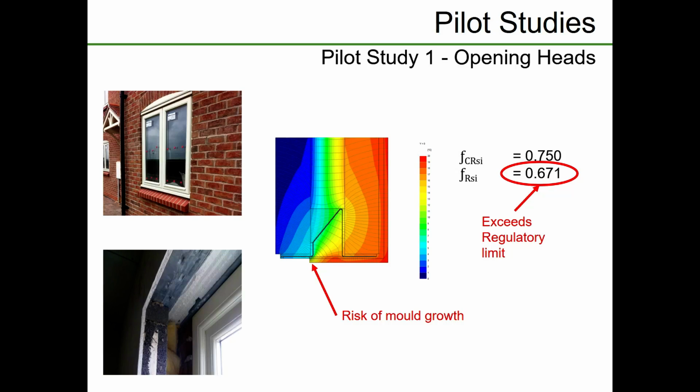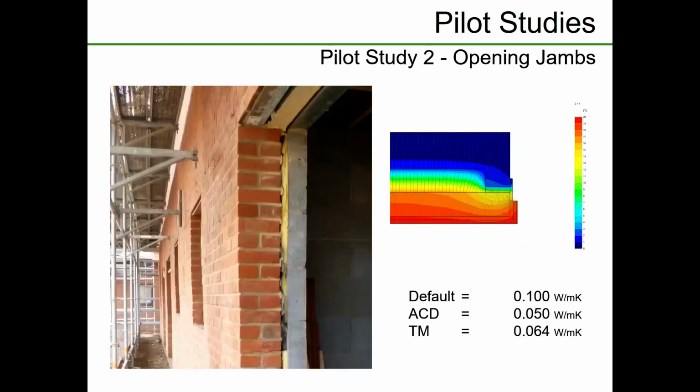There is an issue here as well, that this is full fill cavity insulation and the cavity closer is missing in that instance. It wasn't missing on all of the junctions, so quite why it was missing there I'm not quite sure. Whether somebody would try to put one in and not afterwards, again, we can't be certain. So, these things go on.